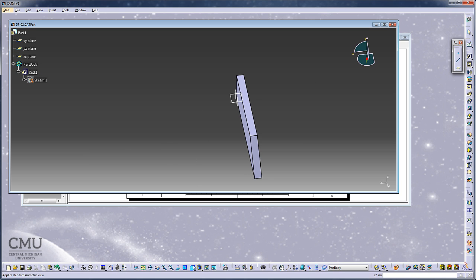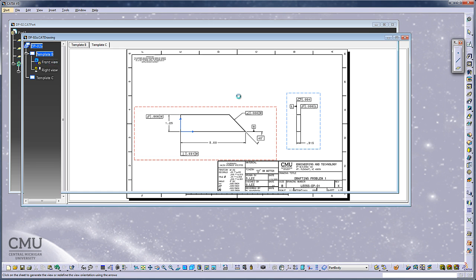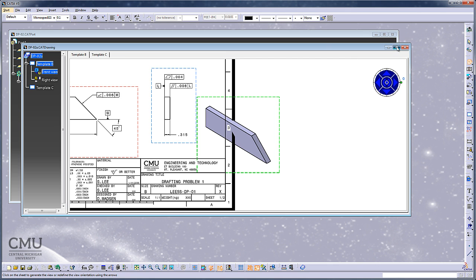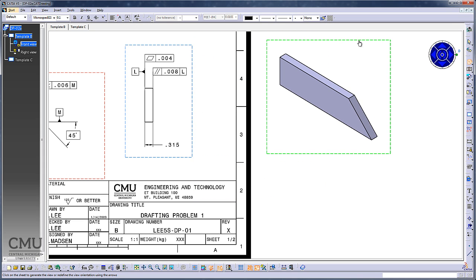That's why I recommended making a part exactly look like the books you're showing. So if you choose very carefully, as you choose isometric view in your part, it will show as a really isometric view. Then if you pick any view now, it will bring it back to you, and then it will let you select the position for your isometric view.